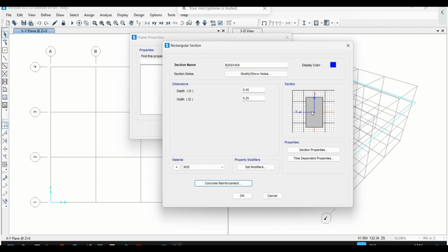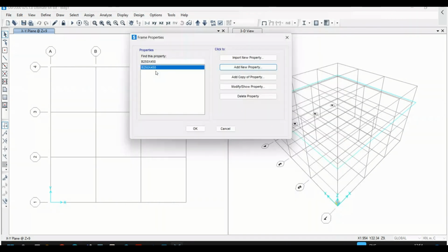The shear distribution can be found in the 1-2 plane, and then in the same 1-2 plane, you will see the major moment where loads are acting on top of this section, like from here, and then rotations or the bending moment will be about local 3. Then you will see major moments about the local 3 axis. So this you should know. That is sufficient for the beam. Next, we'll go with the column.